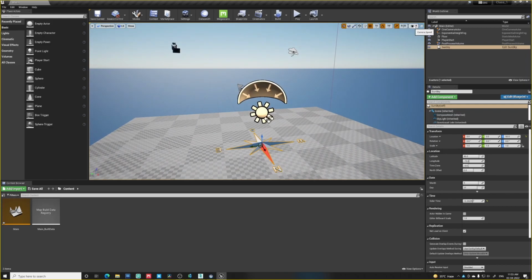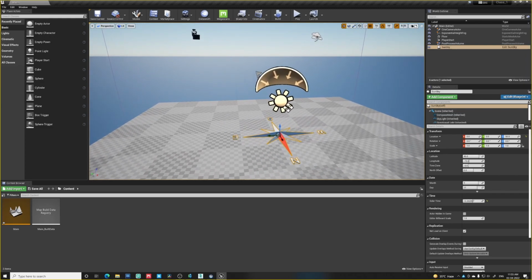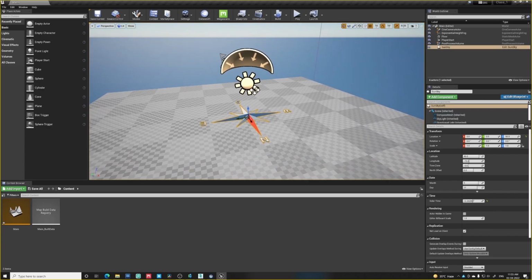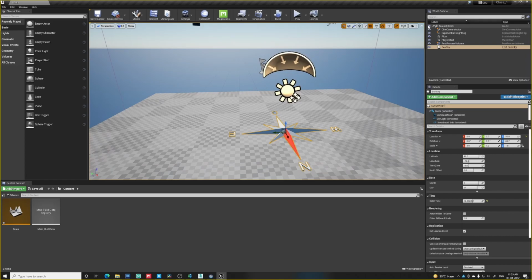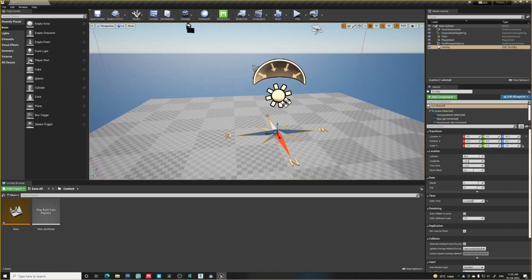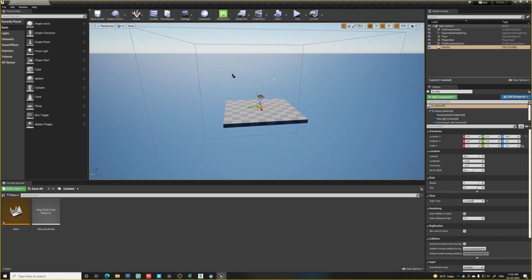And you can actually control the speed here. You have this camera option, the camera speed. Right now I'm this fast. If I want to make this slow, make it 1, so it's now slow. It's in the top right corner, this camera speed. If you hover the mouse cursor on it, it will show you the camera speed. And if I make this 8, now it's too fast.